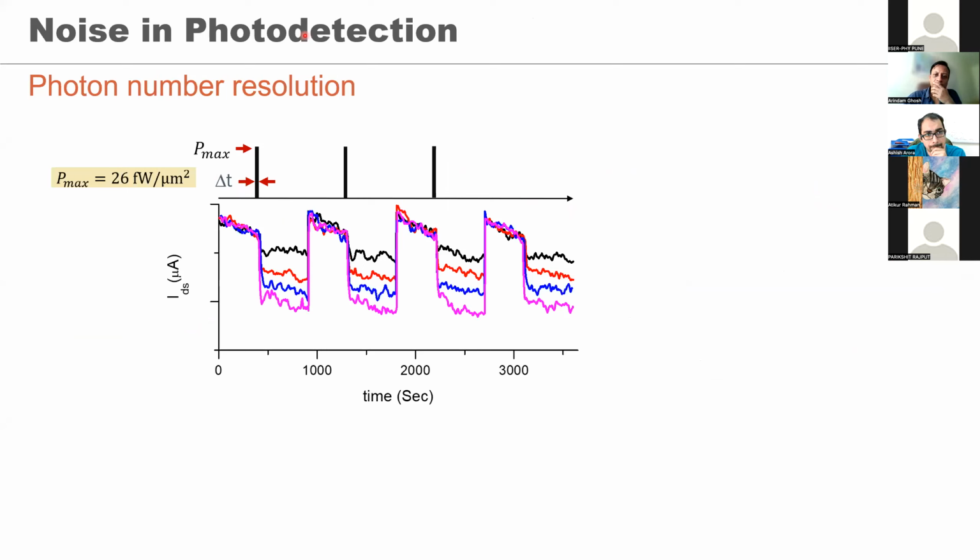I got why it is negative: when you send a pulse in, a lot of charge carriers are generated and transferred onto graphene, and it might be recombining with the holes and reducing the total charge. That is what's happening; it's decreasing the total conductivity. Absolutely correct.